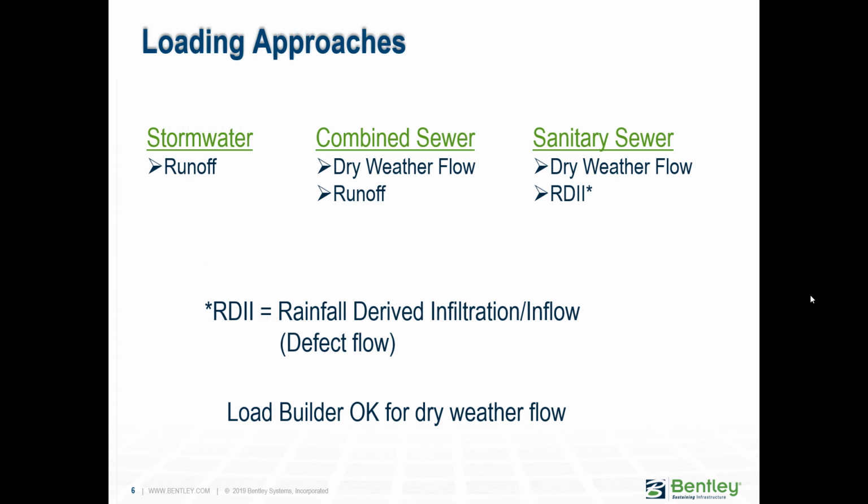Different components are necessary for different systems. Let's talk about the loading approaches. We have for stormwater networks the runoff method, and for combined sewers we have the combination of runoff plus the dry weather flow. And in sanitary sewers we have another parcel called RDII, the rainfall derived infiltration and inflow. It's a defect flow. In SewerGEMS we have the LoadBuilder tool to help with this loading approach.